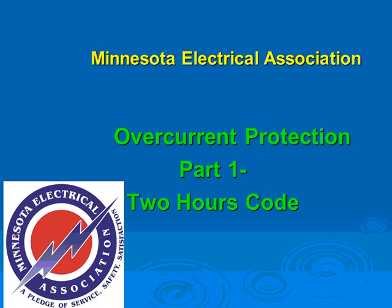So overcurrent, like we said, has three conditions. Condition number one: you grab phase A, phase B, phase C, say on a number 12 THHN conductor, tie them together with a wire nut, and flip on the 20 amp multi-wire branch circuit, 20 amp 3-pole circuit breaker. That's your short circuit. That's the highest amount of short circuit they're going to encounter, from phase A to B to C.